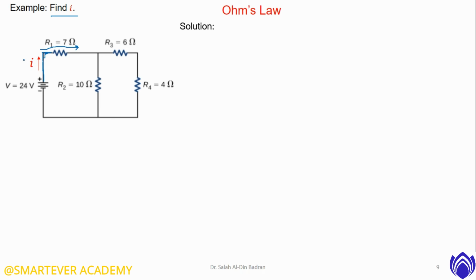Why do we need to understand this principle in general? Because by knowing that this voltage source is connected in series with R1, we understand that the total current is the same as the current flowing through R1. So if we write the current here as I R1, that means the current that flows through R1 is the same as this total current.